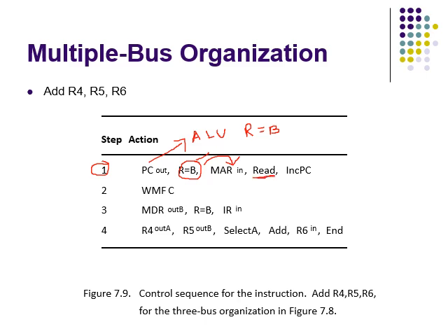At the same time, the program counter is incremented by 4. Note that the value loaded into MAR is the original content of the program counter. The incremented value is loaded into the program counter at the end of the clock cycle and will not affect the content of MAR. So in step 2, the processor waits for MFC and loads the data received into MDR.